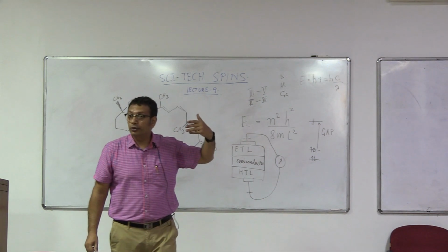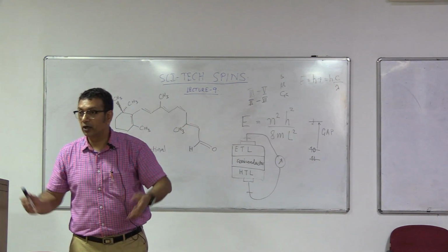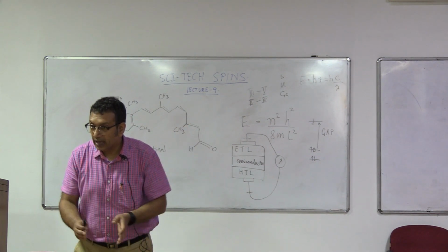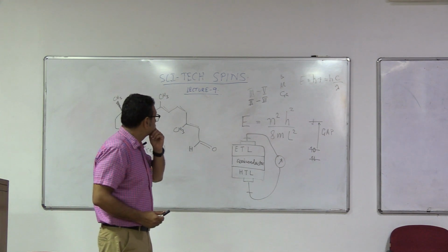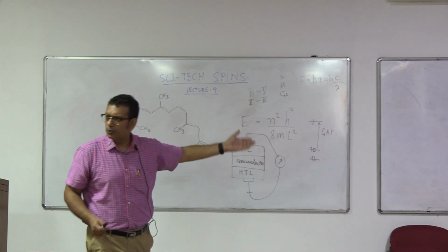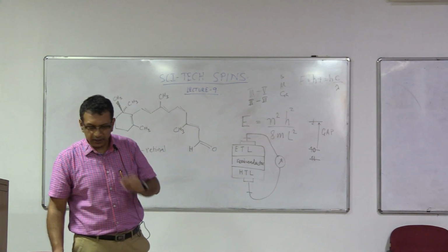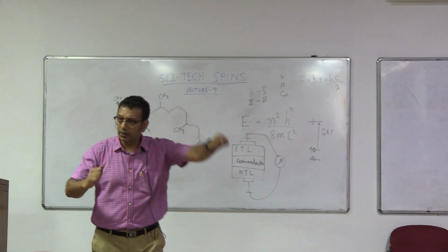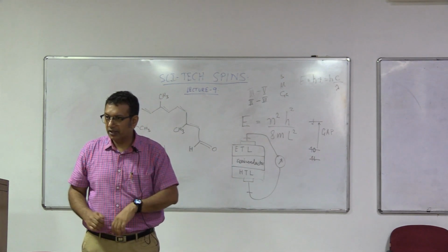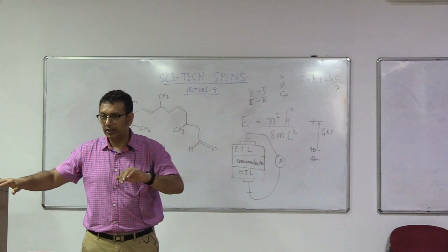You could go on to indium arsenide or gallium arsenide, which happens to be in the infrared. You could just choose one. And actually, I should give you some examples. Gallium nitride, ultraviolet. Indium arsenide, infrared.